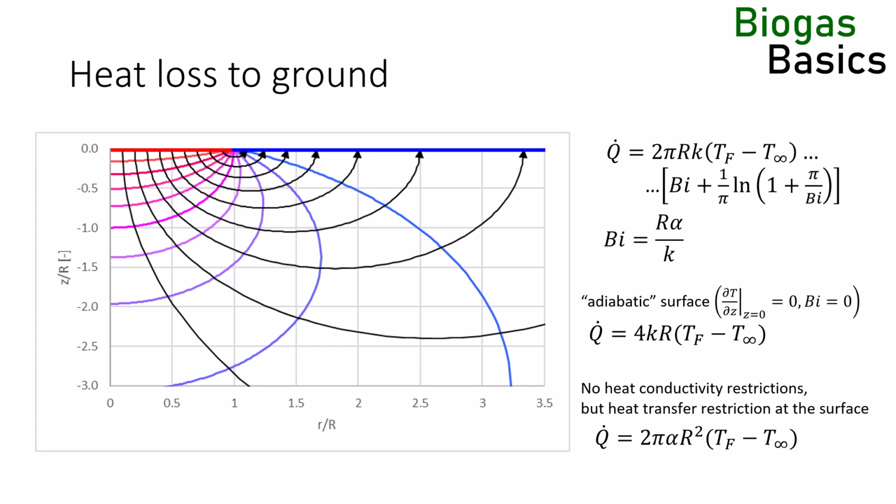When calculating the heat balance, I use the two extreme cases of heat loss into the soil and take the least favorable. If the digester is in danger of overheating, I use a minimal heat transfer coefficient into the ground, which will lead to a higher cooling demand. If the digester requires constant heating, I assume a high heat loss term to ensure that the heating is sufficiently sized. Do not use the formula that relies purely on soil conductivity.